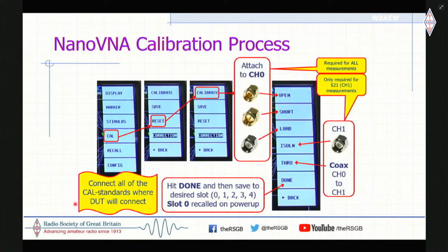And ideally, we want to connect all of those calibration standards, the open, load, and short, to the same location where your device under test would be connected. And that establishes that measurement plane that we mentioned earlier right at your DUT connector.